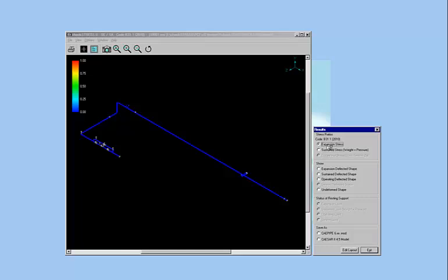So on to the advanced features. Now let's say you're a designer and you have been tasked with identifying those lines that require further stress analysis. The first step would be to run those lines through checkSTRESS, and if you see a blue, it will pass. If you see a red, then it won't pass. Now at this point, you have two choices.